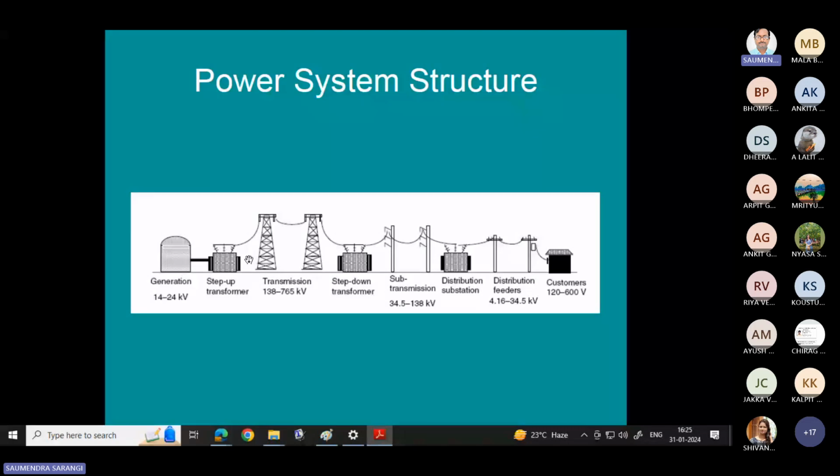So at that point, what do we need to do? We need to operate the breakers we have in the transmission system or the substation, so that the transmission lines will be protected. After that, we go to the point where the fault has been created and the insulators have been burned. After repairing that, we need to restore the power.